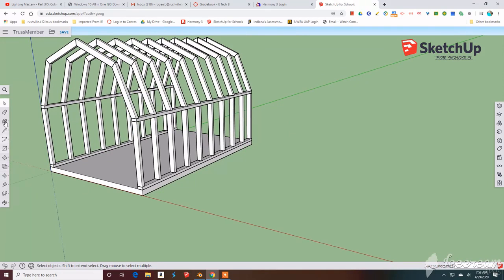What we're going to do is just pick up the rectangle tool, and then I'm going to describe a rectangle just like this. Now I'm not measuring out per se at this point, but I do know some of its dimensions. Like for example, the short dimension here, which is marked with this particular number, we're going to make that 4 inches deep. So let me just type in a number here. Let's call it 48 inches, comma, and then we're going to make it 4 inches.